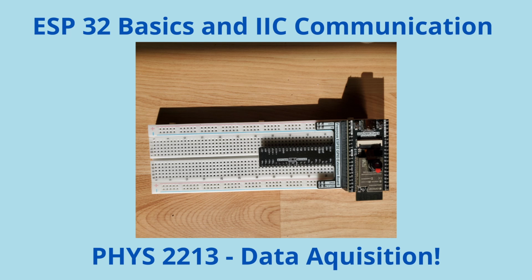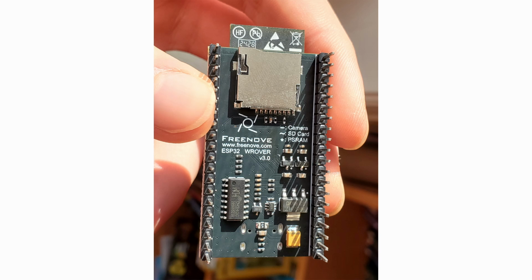Hi there! In this tutorial, we will look at how to connect an ESP32 to your computer, run a simple blink sketch, and then we'll talk about how to use I2C communication to obtain accelerometer measurements. For your computer to identify your device correctly, you will need to install a driver.